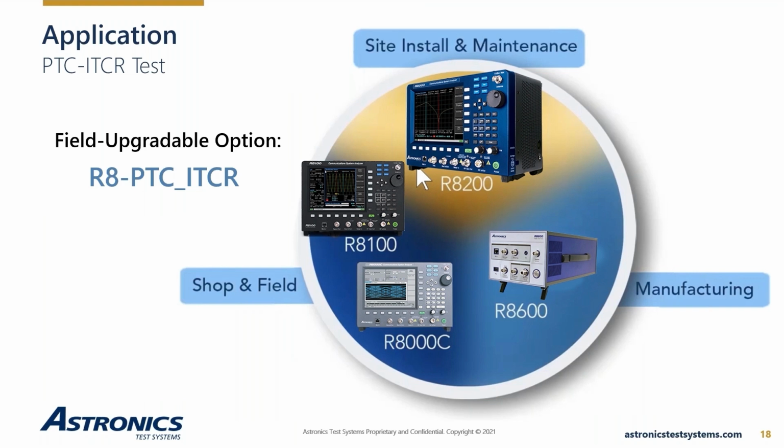So this is primarily something you would use in an automated factory or manufacturing environment, but there may be other use cases as well. And then just this past fall, we released the R8200. This is taking everything that people have come to love about the R8100, adding a single port VNA. What this means is you can now sweep, instead of having to use an external bridge with the 8100, you can now do all of those measurements directly in the box. The module being used for the VNA is extremely fast, near real time, so it's a very good tool if you're doing distance to fault measurements or sweeping filters. It's especially good if you tune duplexers and you want to make sure that your insertion loss is as good as possible. I made a video on this a while back, but anyways, using the vector network analyzer is ideal.